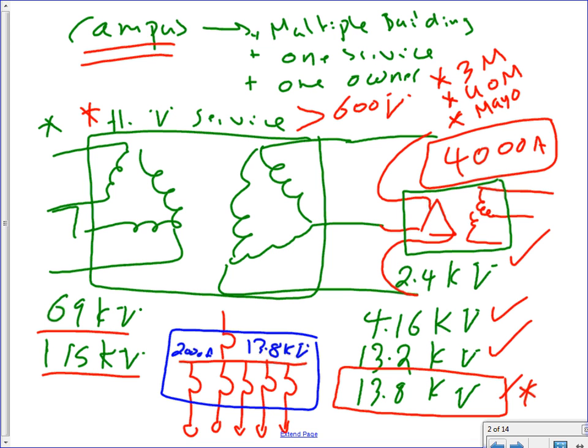So you have 13.8 going through your campus and feeding multiple buildings, from building to building to building, feeding all these loads. When they come with the 13.8, here's the 13.8 landing in the circuit in the switch gear. From the switch gear, they take multiple feeders, 1, 2, 3, 4, 5, 13.8, or they call them 15 kV draw out circuit breakers, that feed 5 buildings here. Every building will have its own feeder, and all of them are 13.8.